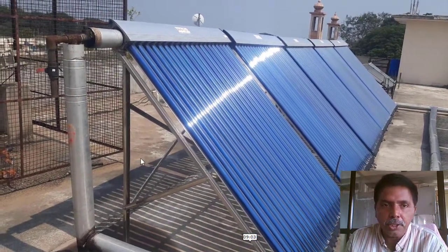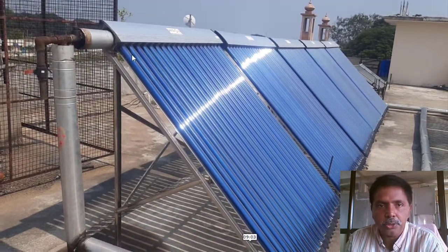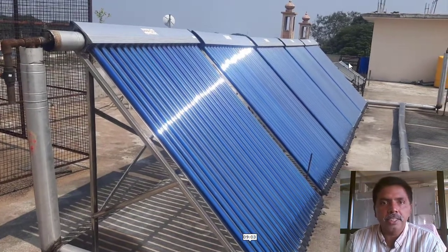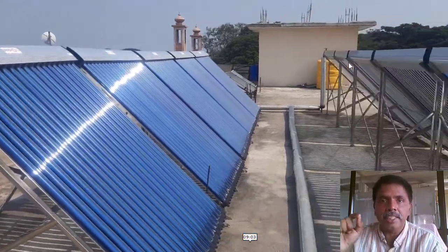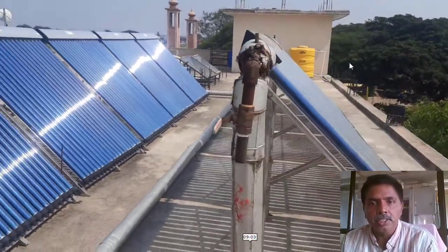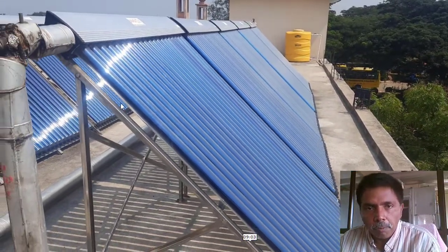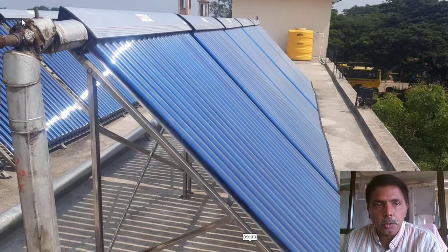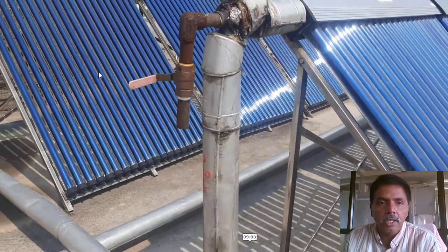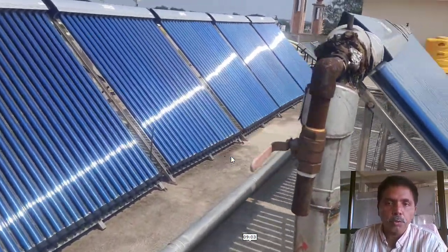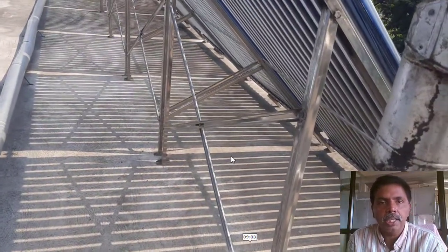This is the heating unit. You can see ETC with heat pipe based collectors. This is not just ETC tubes. Five collectors we connected in series. With a flow rate of 1 meter cube per hour of fluid, we can achieve at least a 10 degree temperature rise. We are using two layers, so 5 collectors in parallel and 2 in series: 2 rows in series, 5 collectors in parallel. So the total mass flow rate we are achieving is 1 to 3 meter cube per hour, according to our need and temperature rise.